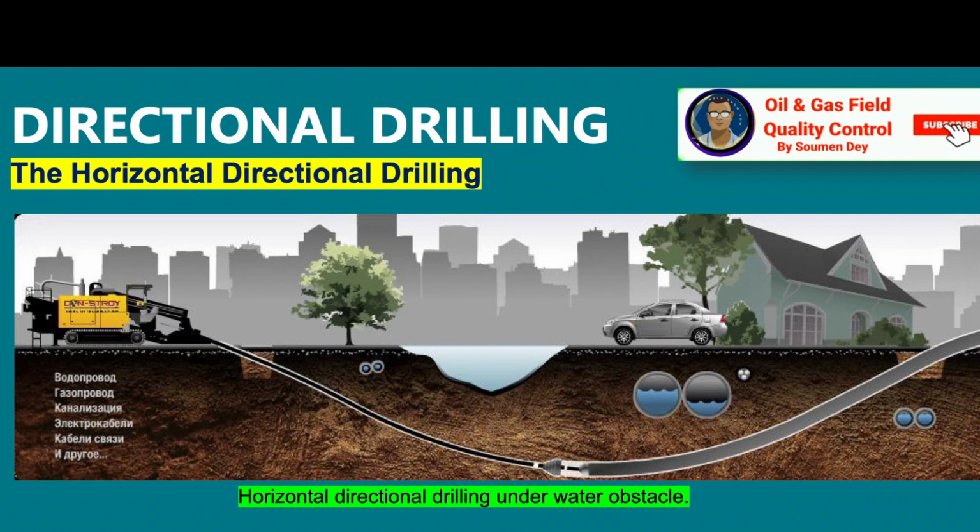The bentonite mortar provides removal of the excavated soil and supports the walls of the well, excluding collapse. The used bentonite mortar is removed with the soil from the working ditch and moved to a dump. A well formed without obstructions and collapses is the guarantee of success and trouble-free work.